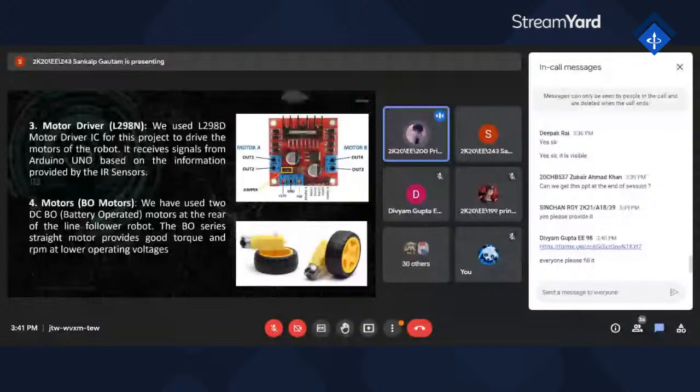In this project, we are going to use the L298N motor driver, which is a dual H bridge motor driver and is sufficient for our two motors. It allows us to control the speed and direction of the two DC motors that we are going to use in this project, which are running at the same time. So that's how it helps us in this project.